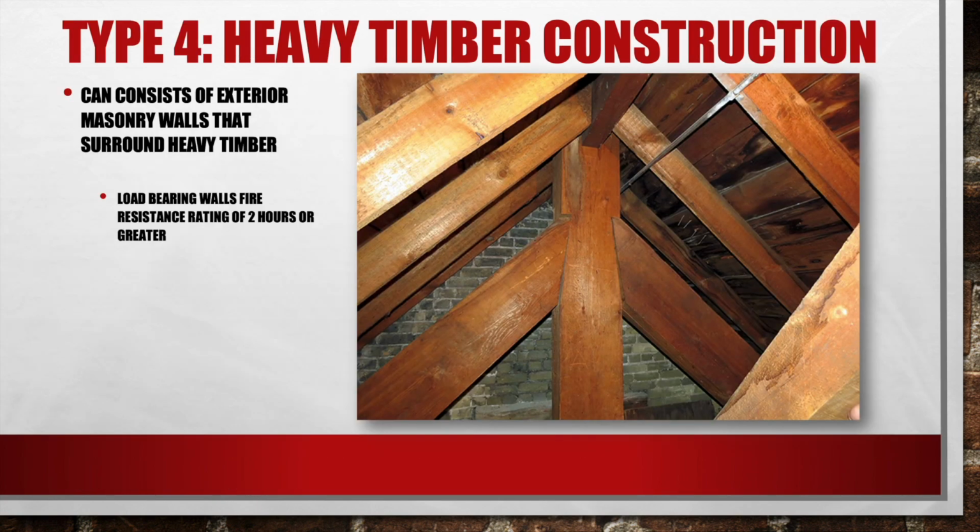Okay, now I'm coming back to Type 4, heavy timber construction. This can consist of exterior masonry walls that surround heavy timber. So your load-bearing walls, and this is important to remember, have a fire resistance rating of 2 hours or greater, so a minimum of 2 hours. And I want you to remember that coming up. There are not supposed to be concealed spaces in these buildings. If there is, it's because somebody has done a renovation in the building. And you normally find these in older buildings.